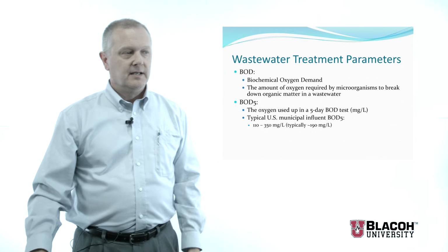We pull it out, we measure the dissolved oxygen concentration, we know how much oxygen was used up, and that becomes then a measure of the biodegradable organic material that was in that wastewater that we put in the bottle. Okay?